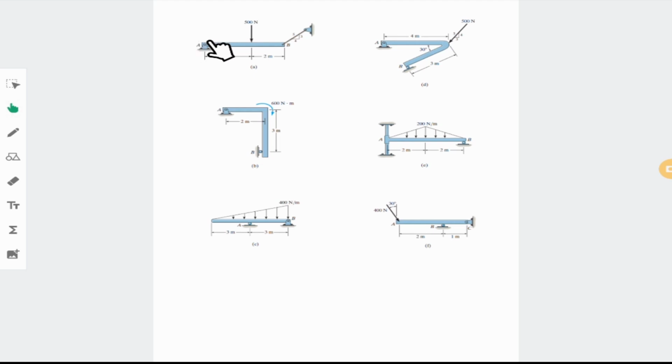In the last session we said we need to put the forces based on the joints that we have. For example, the hinge does not let me go up, or to the left and right, and that's why I would put two forces, but the hinge lets me rotate. Let's forget about the rest of the mechanism.